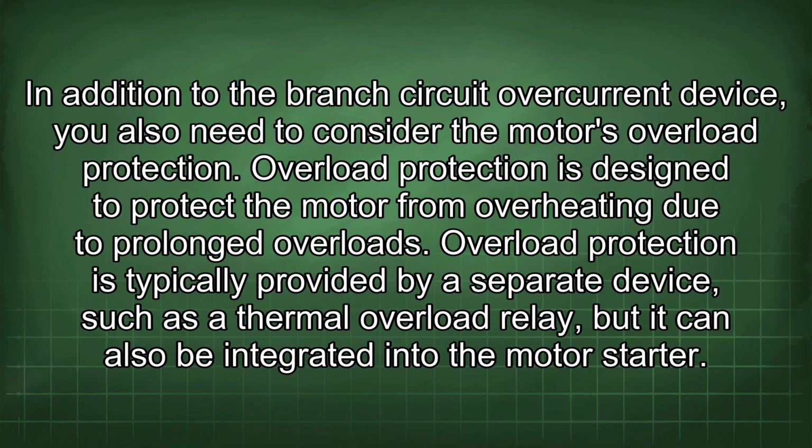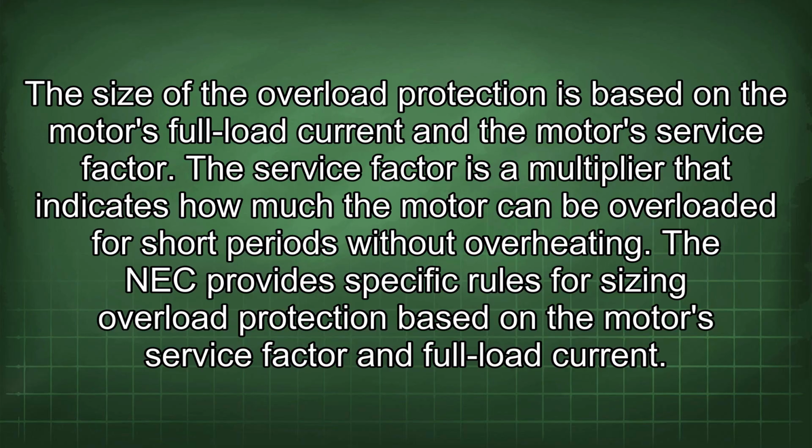In addition to the branch circuit overcurrent device, you also need to consider the motor's overload protection. Overload protection is designed to protect the motor from overheating due to prolonged overloads. Overload protection is typically provided by a separate device, such as a thermal overload relay, but it can also be integrated into the motor starter. The size of the overload protection is based on the motor's full load current and the motor's service factor. The service factor is a multiplier that indicates how much the motor can be overloaded for short periods without overheating. The NEC provides specific rules for sizing overload protection based on the motor's service factor and full load current.